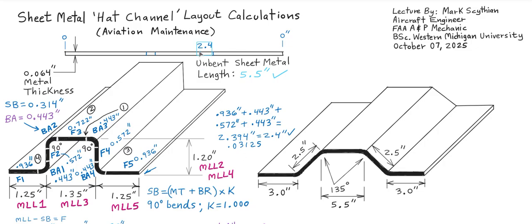So you'd start your bend right here, and this section would curve into this bend allowance right here. Because these are symmetrical with respect to the right outboard and the left outboard, after making this bend here, you'll get a long right angle.